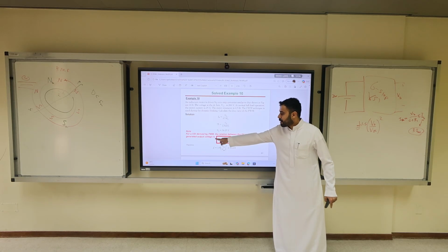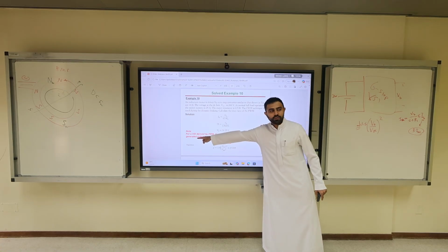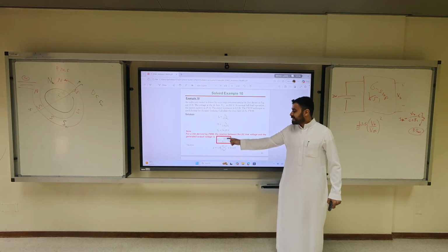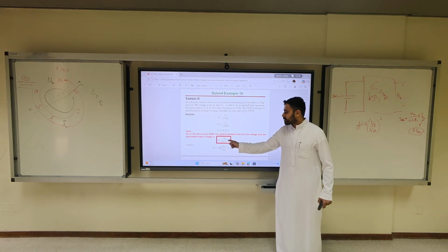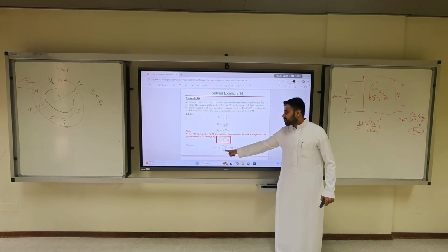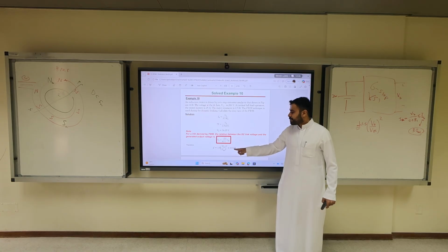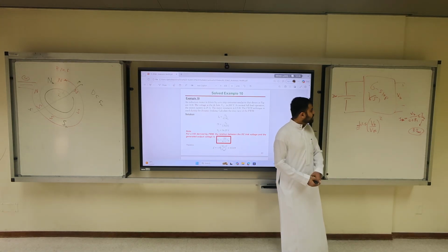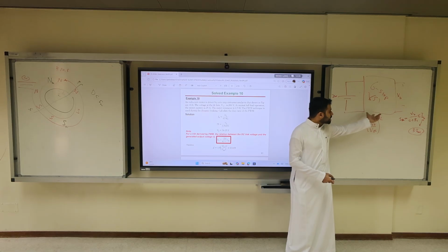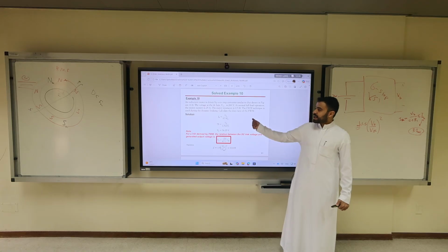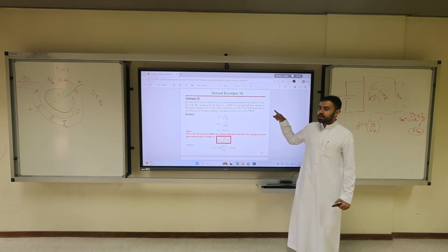Now, using the power electronics, the VSI voltage source inverter is driven by a frequency modulated signal. The relationship between the duty cycle and VDC and VB is D equals 1.5 times (VB over VDC) all squared. So in this example, 1.5 times (56 over 200) all squared is 0.119. So the VSI has to give a duty cycle of 0.119 to achieve dynamic braking for this example.